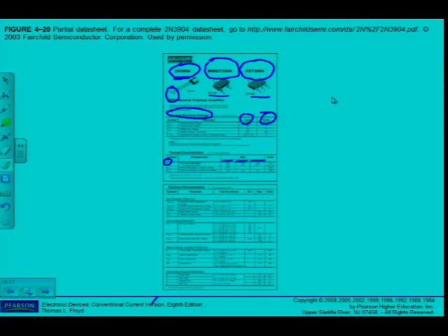The 2N3904 is 625, and the unit is milliwatt. The MMBT3904 is 350 milliwatt, and the PZT3904 is 1000 milliwatt, or 1 watt. Now just below the total device dissipation, you can see there's a line that says derate above 25 degrees Celsius. Now that's the important one, eh?